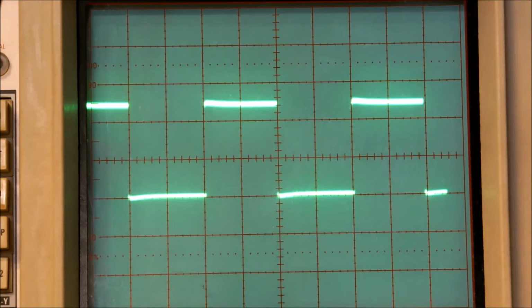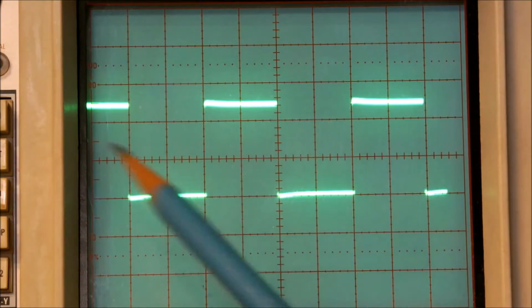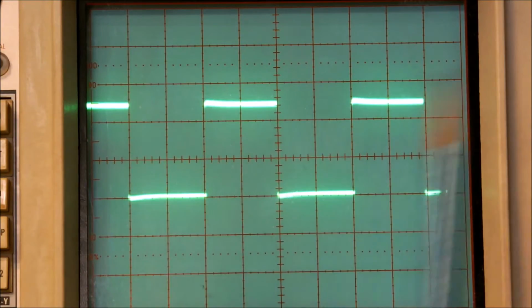milliseconds. If we want to express that in frequency, the time per second frequency in hertz is actually the cycles per second. They mean the same thing. So we use that measurement a lot to express the characteristics of a waveform, and we'll say that the frequency of that in this case would be 1 divided by 1,000 divided by 2, which gives us 500 cycles per second, or 500 hertz. I think you can see the relationship between those different measurements.